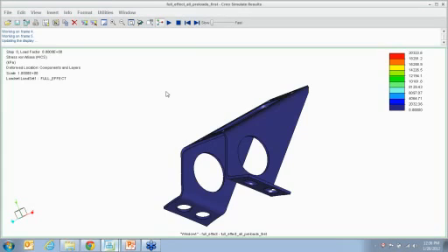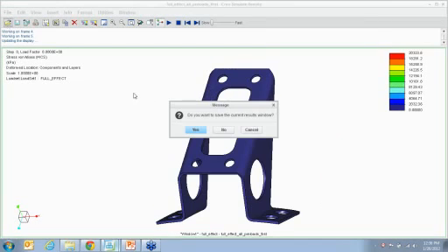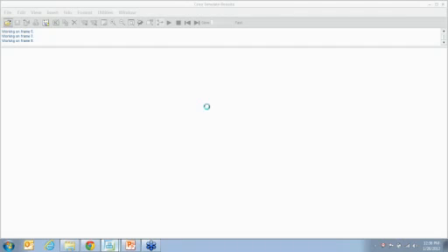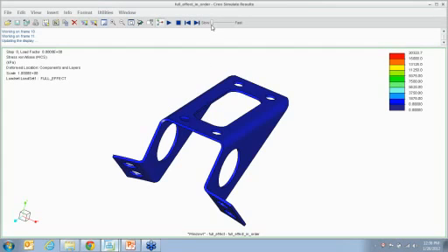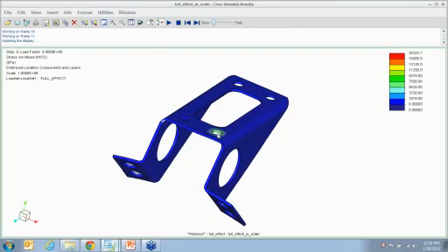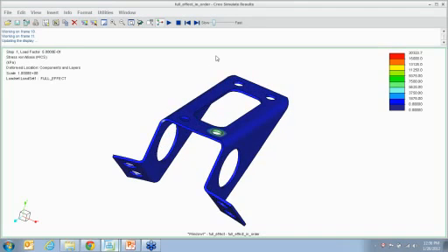Now, if you want to compare that with what happens when each bolt is tightened according to the order that we put the loads in? So see, the deformation is different. So this is bolt number 1, this is bolt number 2, bolt number 3, 4, and then you kind of push this up.